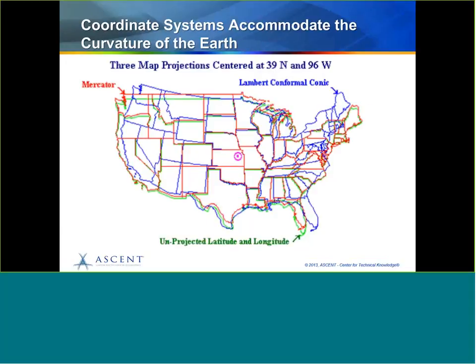All right. Now, of course, the reason it's so very important is because if we don't set that coordinate system and we bring our data in, we're going to have to manually set the scale, set the insertion point, set the rotation value, and we want to make sure that we don't have to do that work. We can see actually here how projection systems work.